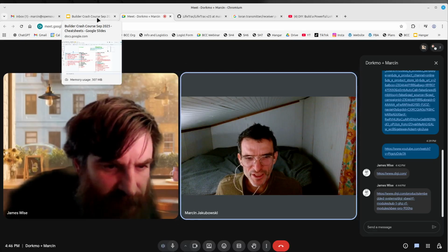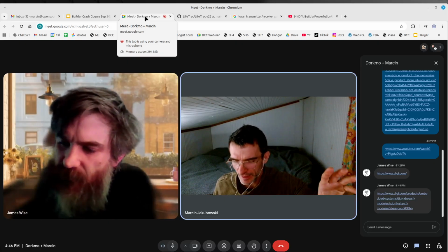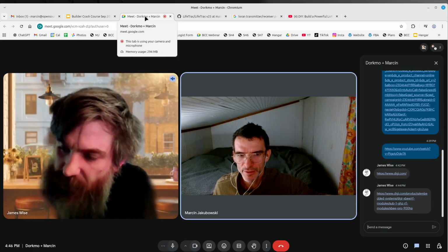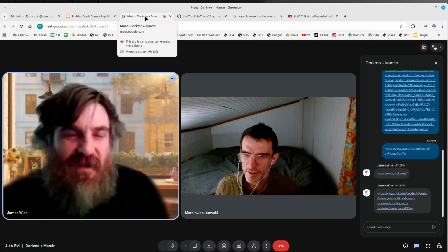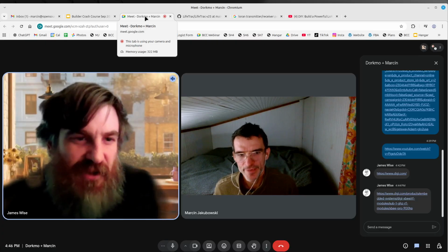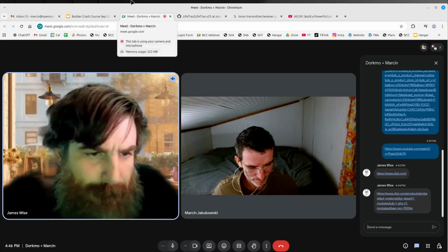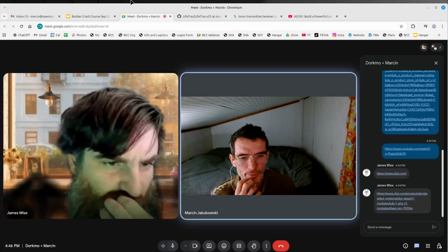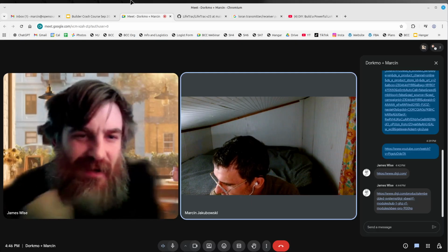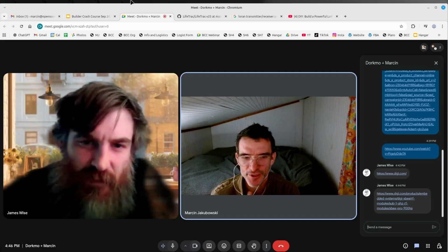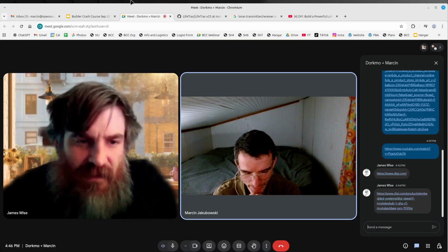And that's for open center, so we just get constant flow. It doesn't require a variable flow pump. No, it diverts on a percentage basis, 0 to 100%. That gets you some control. I don't think those are truly accurate, like the ones with gears inside. Right, it's not that type. It's just a valve spool thing.